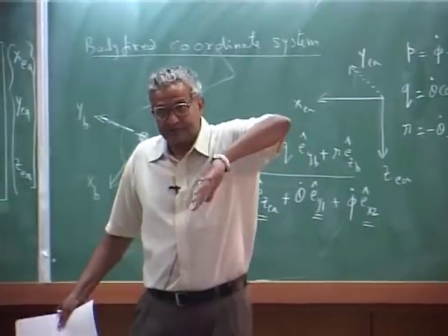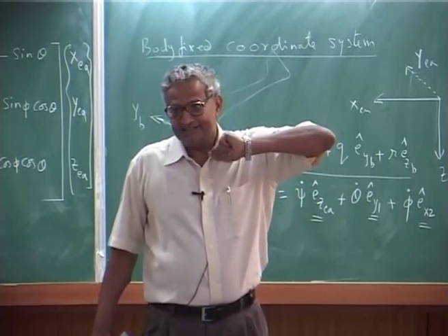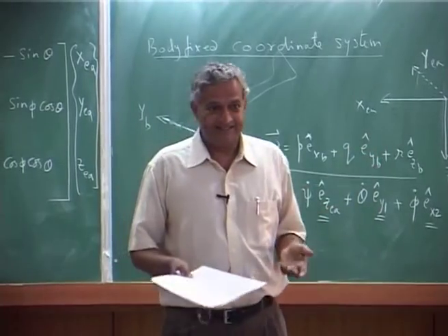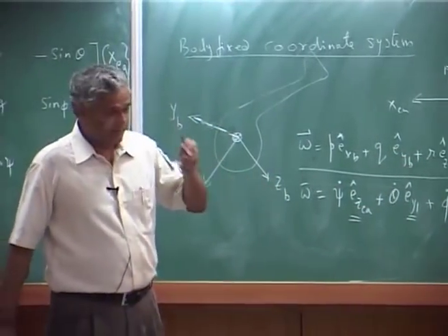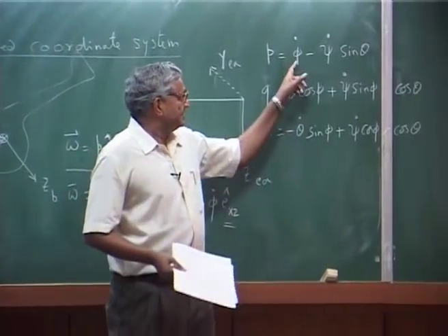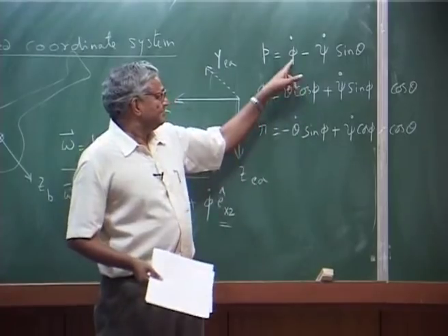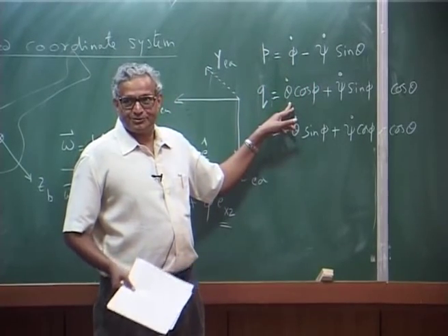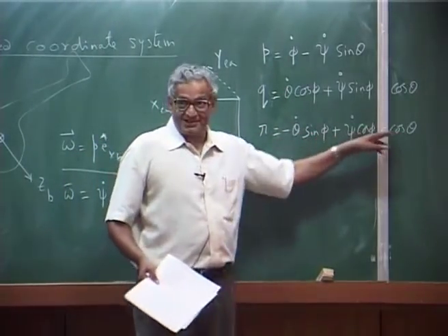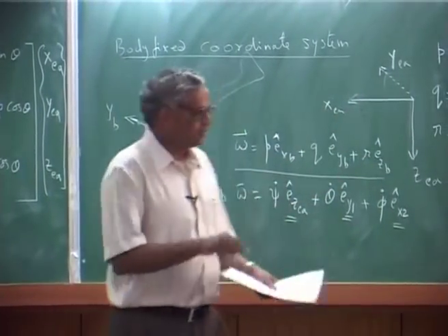because orientation of the vehicle can be with respect to earth axis in any orientation. You always want to know what orientation it is in. So, particularly if you are designing any autonomous vehicle, you have to know all this and the estimation of this. Okay. Now, you can always solve for this in terms of PQR also, that is, psi dot, phi dot, theta dot in terms of PQR, but again theta and phi will be sitting there. So, this is just a transformation of one coordinate to the other. We will not use that.